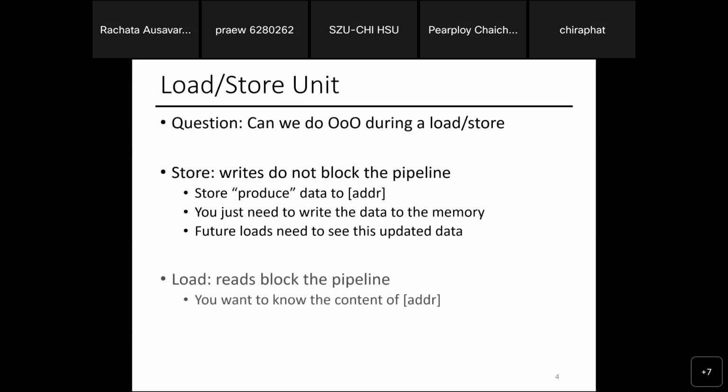All right. The load, that's the one that blocks your pipeline. So in CPU design, reading the data is really important. You want to be able to service reads really quickly. Writing the data is another myriad of problems that has to do with coherency and consistency. Can everyone see this updated version of my data when I write to it? But that's a totally different problem that we are not going to talk about today. Okay.